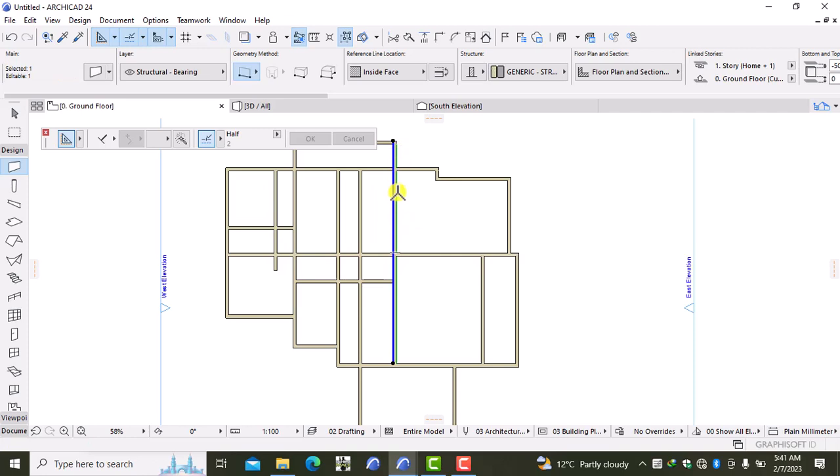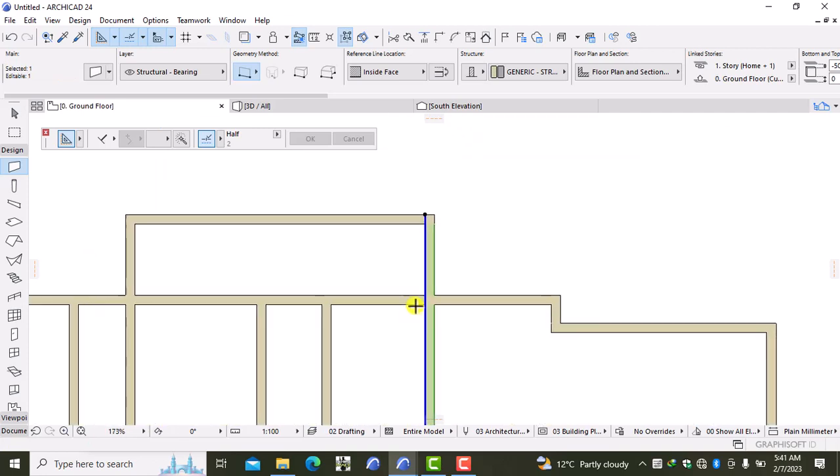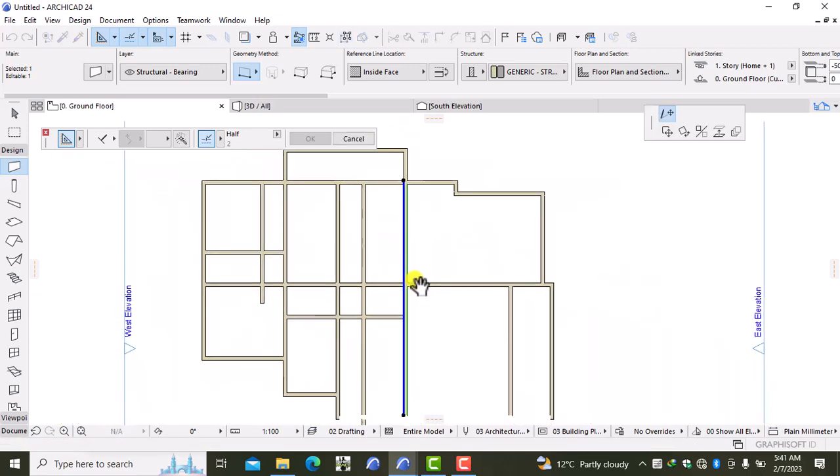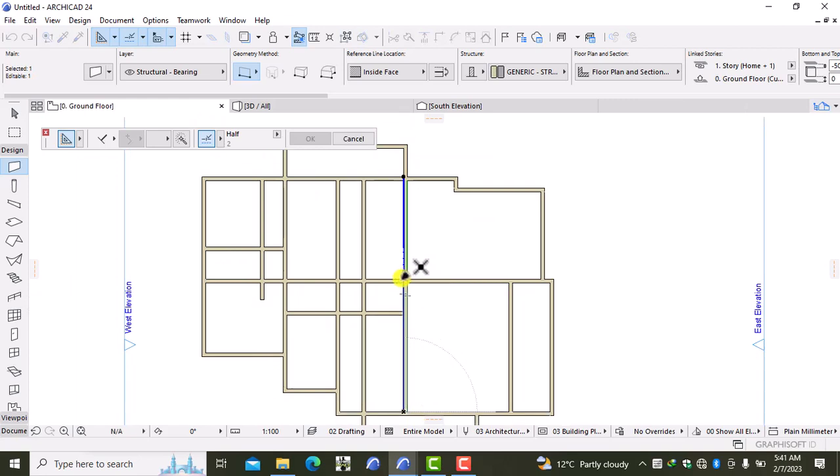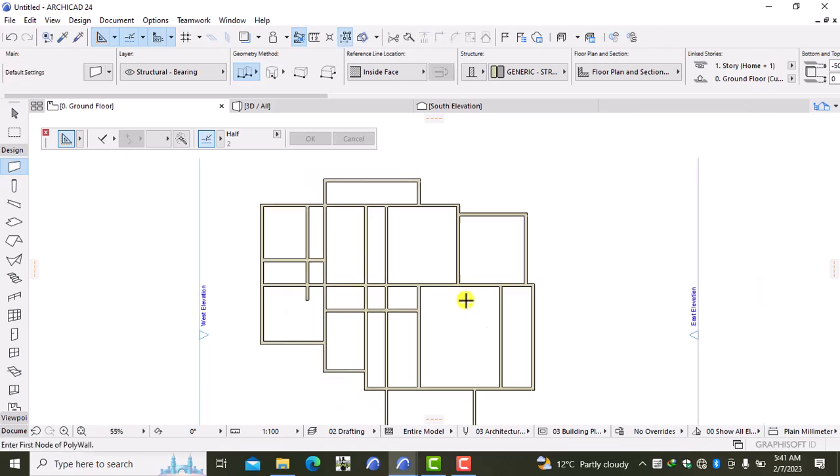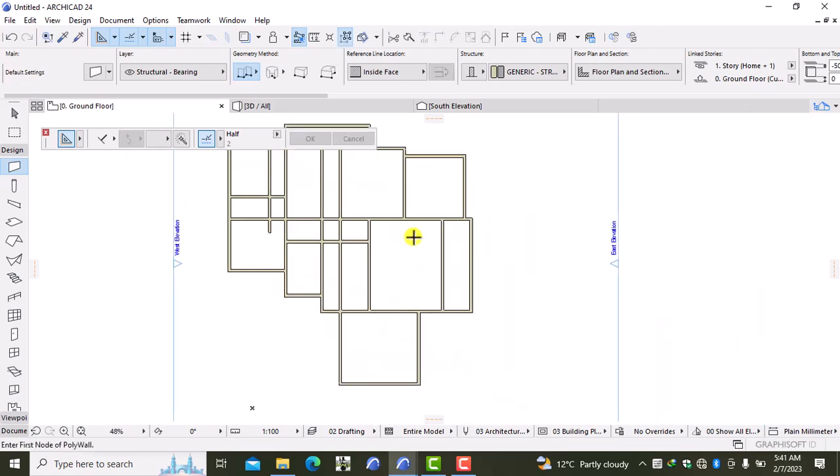Also this one, we need to split this. So once I select this one, I'm coming to the split tab over here, and then just go ahead and cut it like that, and then I can drag this node from there to this point, to that point, and then from this point I can do a wall that's coming all the way to that point, and then just escape.